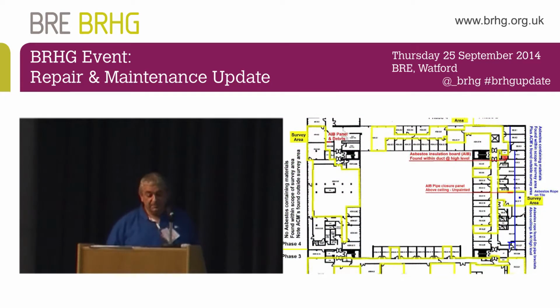So going back to this plan, I've already gone through it, but you can see we found two extra things there. It's nice and clear. I think it's nice and clear. Am I wrong? Please tell me if I'm wrong. It needs to be in colour, not black and white with little sample numbers saying this is asbestos. Your builder needs to be able to understand this. The pipe fitter needs to understand it. Nice, bold colours.